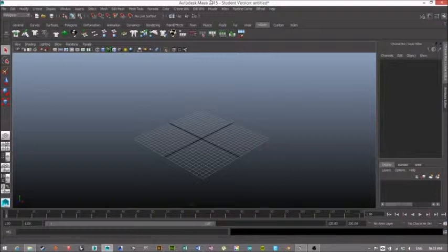I'm going to show a lot of NURB stuff today, but what happens, especially with blend shapes, and one of the first things we'll talk about, is that when you're blending between two objects, the objects have to be topologically similar. So you can't take a mesh of a house that you guys have designed and a sphere and just make them the same thing. But if you started with a sphere and never changed the face count, and you modeled the house out of that, which is super easy and is actually how you do mesh modeling, out of a simple primitive, then you absolutely can blend shape between the two of them. If you don't blend shape though, there are other options. You just have to get clever with it.